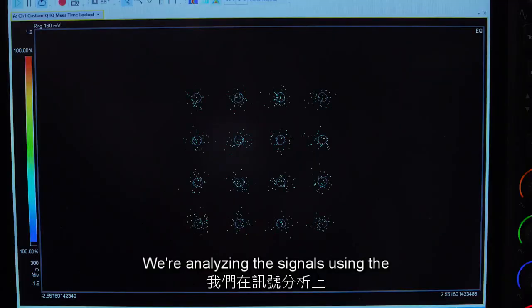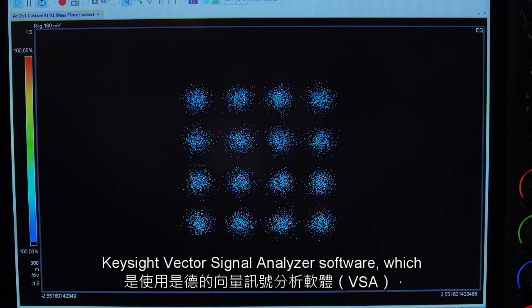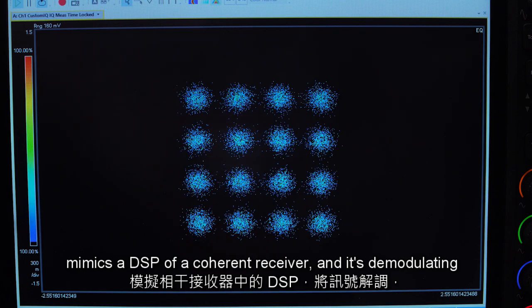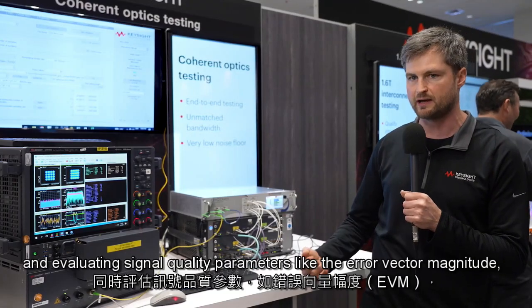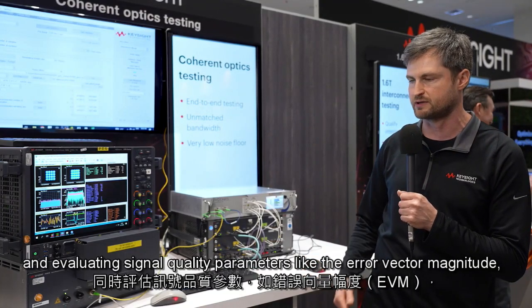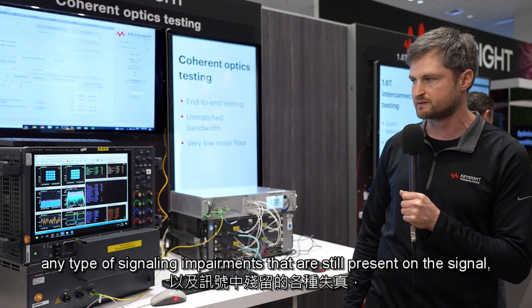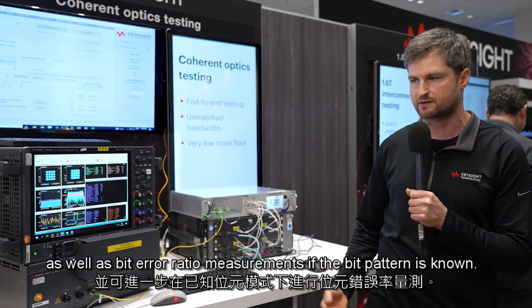We're analyzing the signals using the Keysight Vector Signal Analyzer software, which mimics a DSP of a coherent receiver, and it's demodulating the signal to show constellation diagrams and evaluating signal quality parameters like the error vector magnitude, any type of signaling impairments that are still present on the signal, as well as bit error ratio measurements if the bit pattern is known.